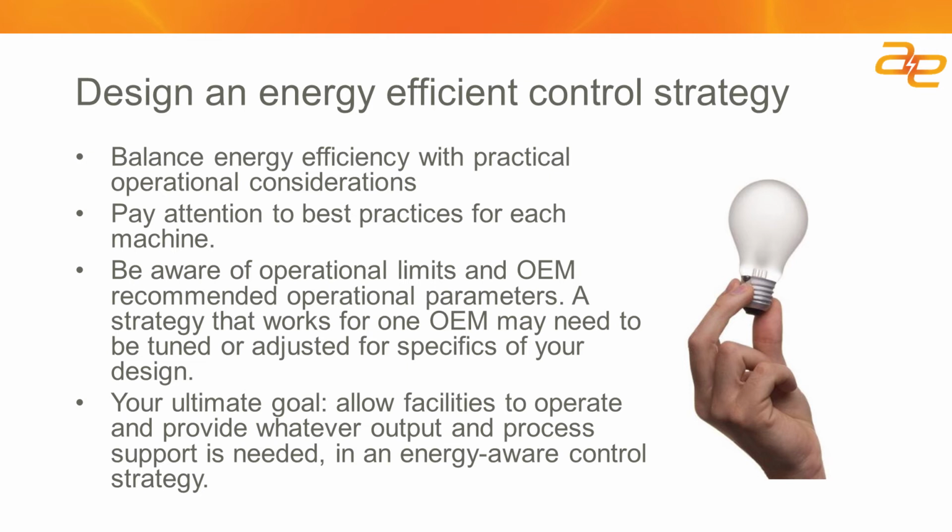I mean, that's really, in a nutshell, the idea behind equipment sequencing, but also taking into account that part of your design has to be best practices related to determining the set points at which you would transition or cycle on a new machine, as well as cycle off a machine, and also the procedures around prioritizing how you accumulate runtime on those machines to not only address the load with the appropriate capacity, but also minimize the energy or the impact on the environment, and maximize the lifetime of the equipment.